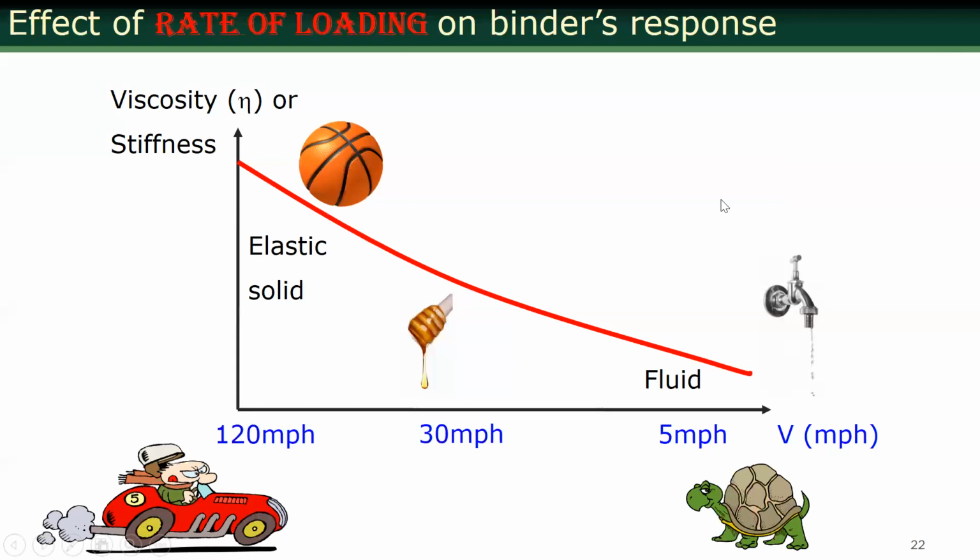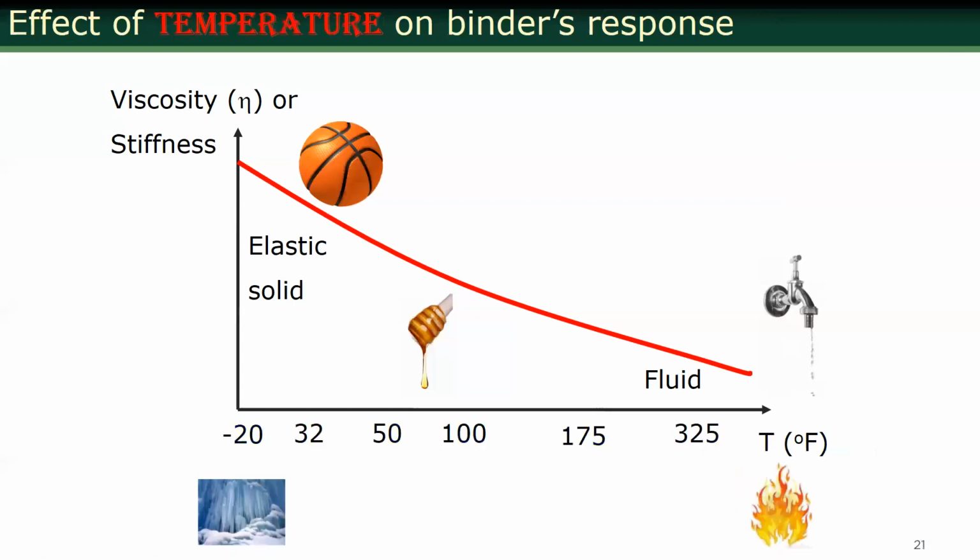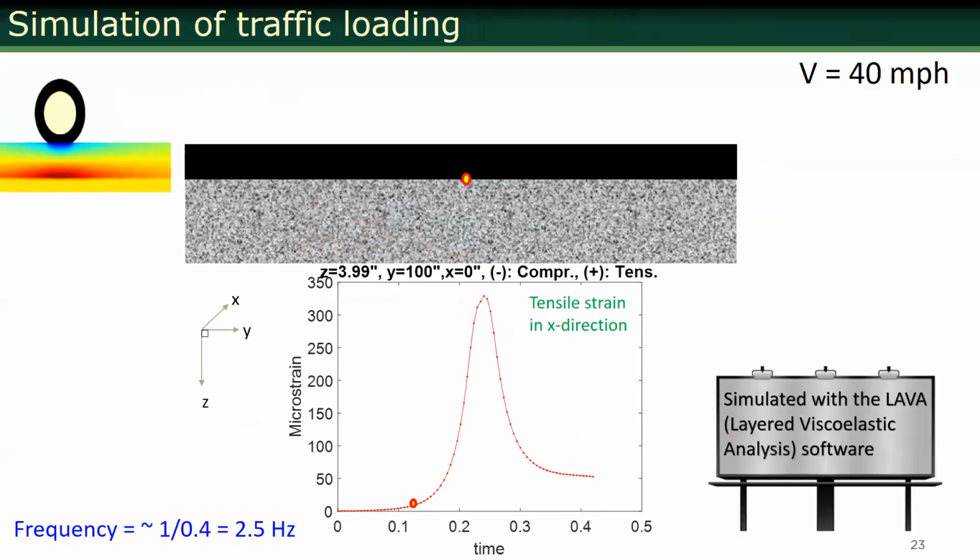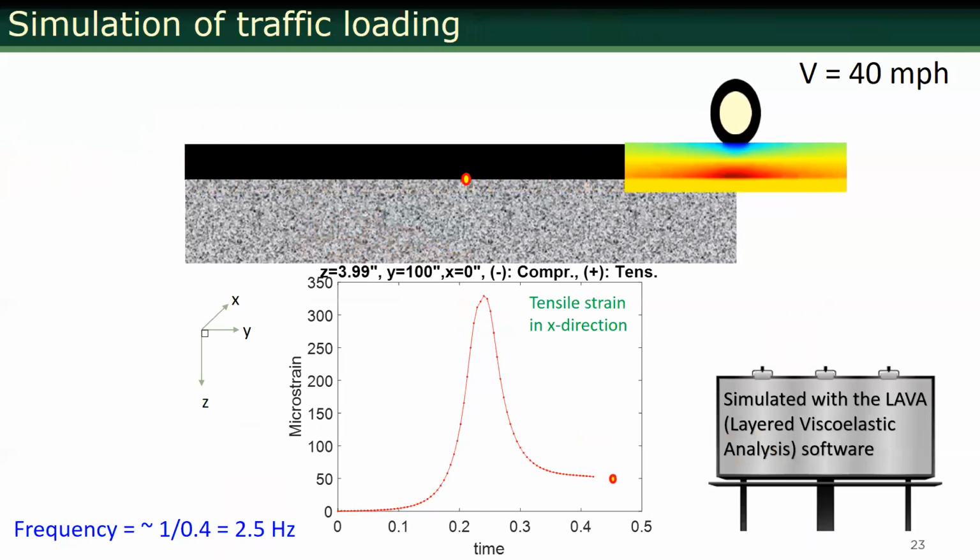Okay. So rate of loading or time, please put a note: time and temperature. There's something called the time-temperature superposition principle that we're going to talk about today because we use that in Superpave binder design. Time and temperature are interchangeable in the properties of the binder. They are interchangeable. I'll talk about that later. Now let's go back to scale 1, which is the pavement structure.